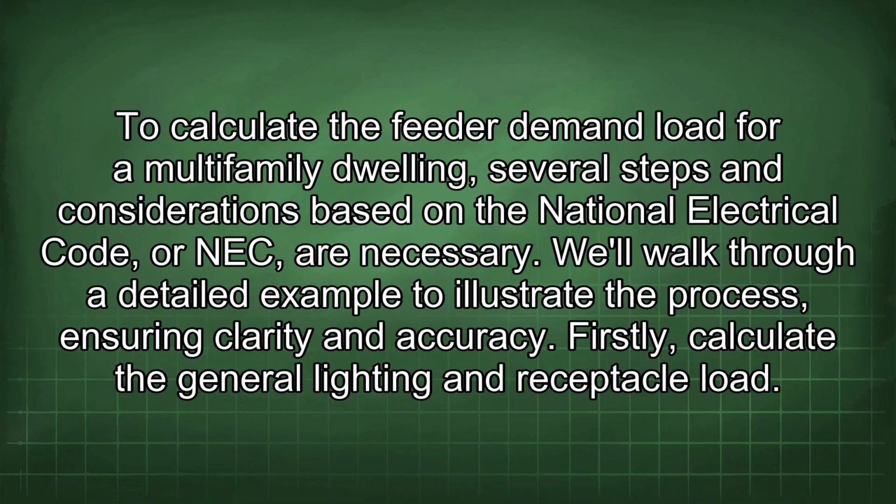To calculate the feeder demand load for a multifamily dwelling, several steps and considerations based on the National Electrical Code, or NEC, are necessary. We'll walk through a detailed example to illustrate the process, ensuring clarity and accuracy. Firstly, calculate the general lighting and receptacle load.